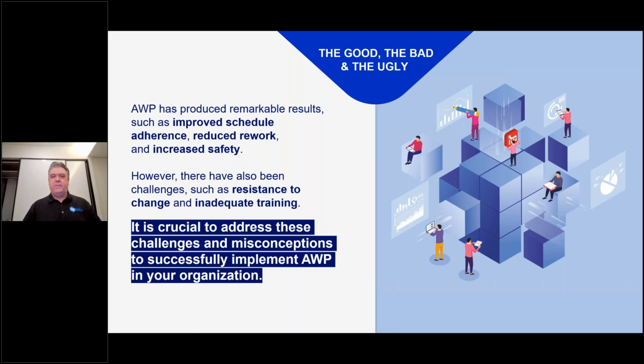AWP was developed as an owner-driven initiative to get visibility on where we are at. So as an owner team and a project management team with the prime contractor, we can come in and work with the contractors in a lot of the constraints. If you do a constraint analysis, most of them end up in the lap of the EPC coordinating across the trades. You don't build IWPs for a single discipline, which if you read some of the literature, you might believe, well, I'm planning just a discipline alone.